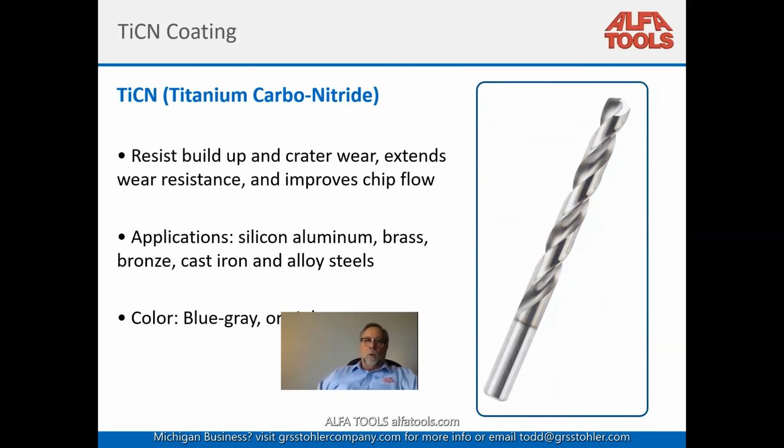So that one is gold. And by the way, if you're over in Harbor Freight or Lowe's or whatever, and they got these gold drill sets, take a good look at them versus a real tin coated drill. I mean, that's some kind of flash coating. It's not real tin.